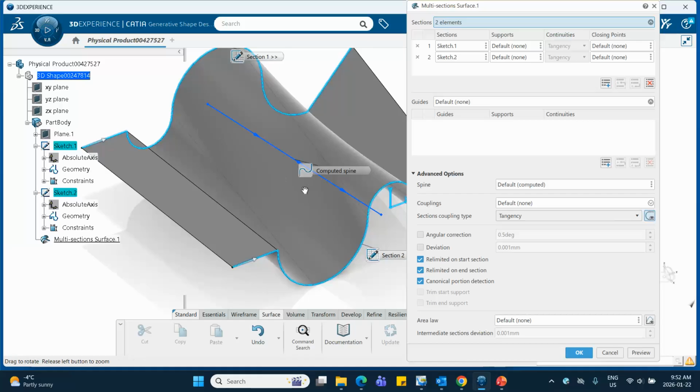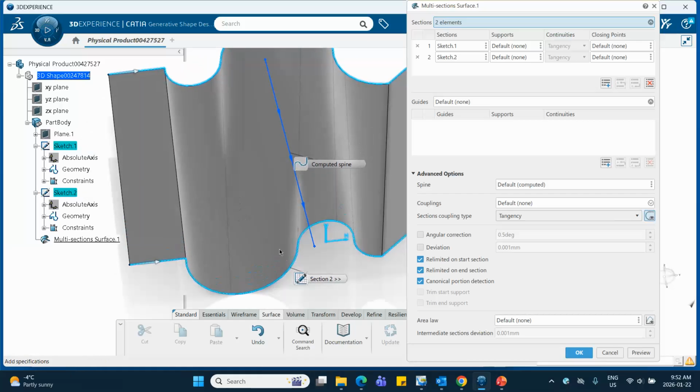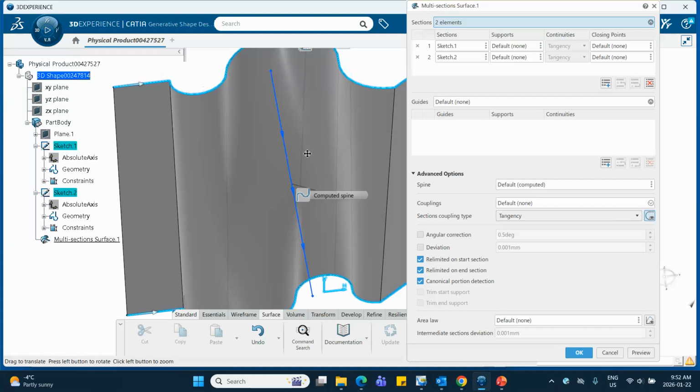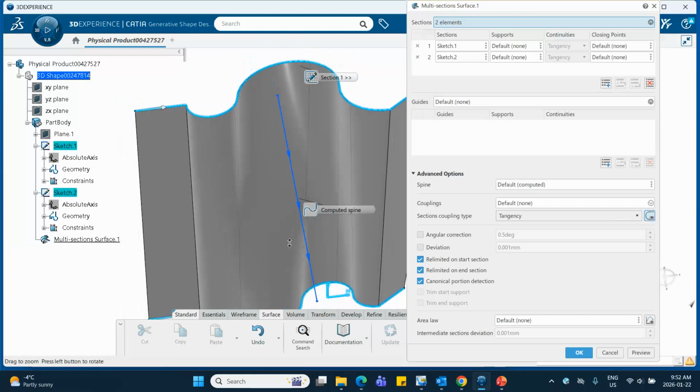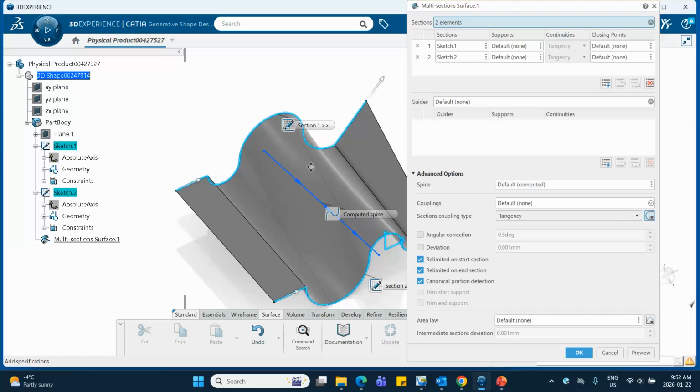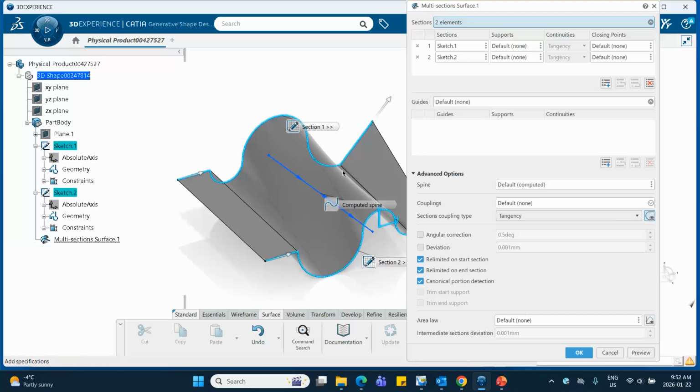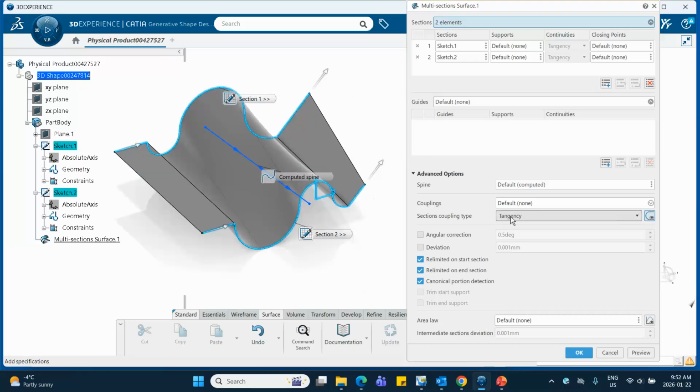Okay, notice that those points are not connected directly to each other. They are connected somehow. For example, this point may be connected to some other location over there, but it is not quite what we expect. Okay. Remember, tangency means just connect the points that the tangents are discontinuous. But when we do tangency, then curvature, it connects also the points where the curvature are discontinuous, namely these places where the arcs come together.